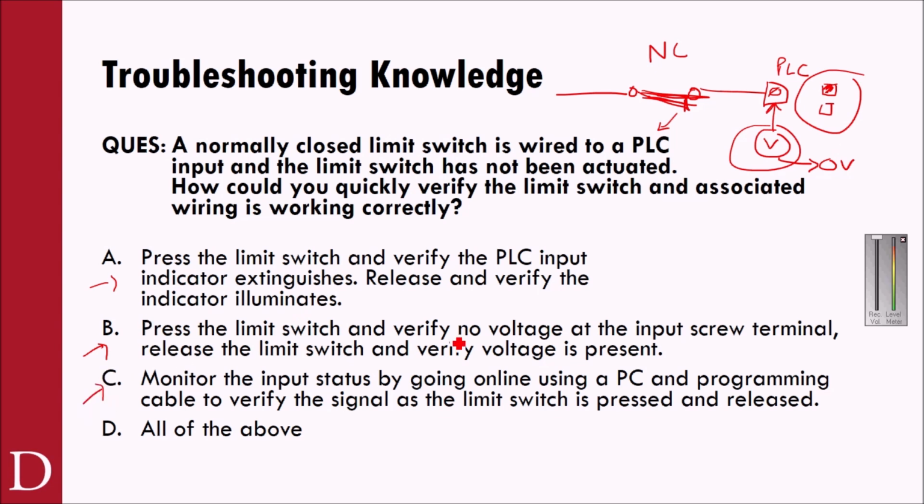Could I monitor the input status by going online using a PC and a programming cable, to verify the signal as the limit switch is pressed and released? Absolutely, you could. I would say, as far as order, I'd probably do this one first, this one second, this one third, depending on the situation I'm in. But the answer to this is any one of those would tell me if that limit switch is working right. It's going to give me a visible indication of whether that limit switch is providing voltage to the input or not providing voltage to the input.